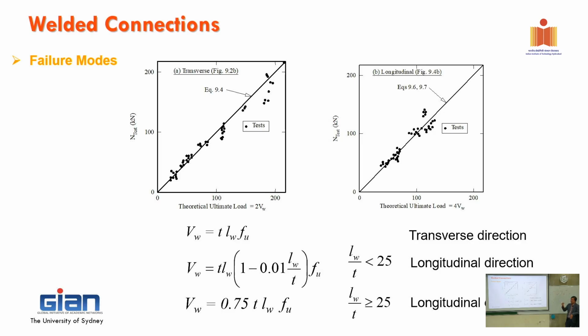So once you have the weld, the classification of the weld, and you know FY and FU of the weld, they just use that. Is it inbuilt in the FU itself, or is it only the material ultimate stress FU? It's a material property of the weld. Yeah, they calibrate based on that, to make it simple. But you can see FU is the ultimate one. Of course, you get it from the test and then from the classification that you have.